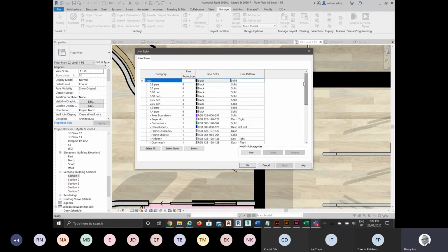Okay, so it's quite simple. You have a line weight, right? So 1 being the lightest, and 15 or 16, I don't remember, I think it's 16, is the heaviest. I never go that high, so you don't need to really worry about the heaviest lines. Probably 7 or 8 is about the heaviest you'll ever need. And I'll show you the line weights in a minute. But again, you just have a number for the line weight. Just remember that.